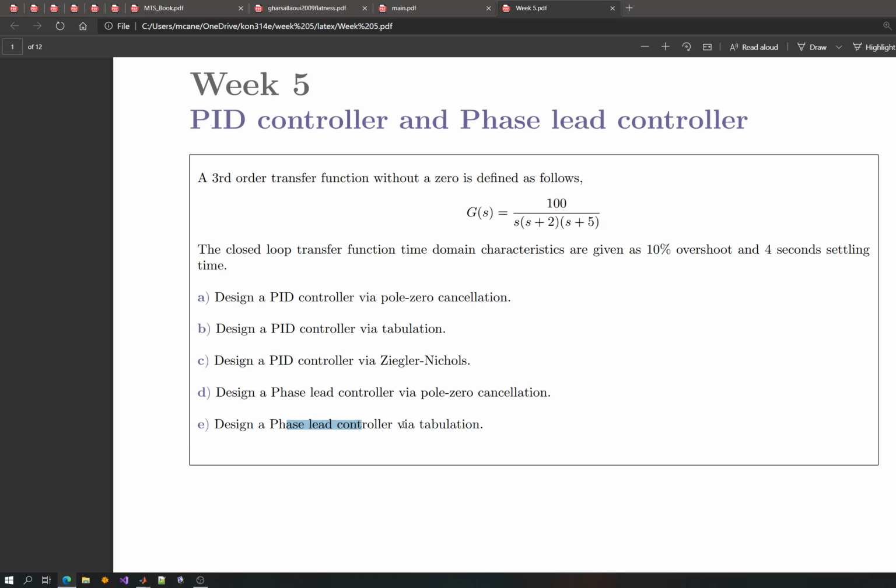It is very important to have an integrator in the forward path, which means that somehow you have an integral of the error somewhere, or if it's needed, the double integral of the error. So we will come to that in the upcoming lectures.